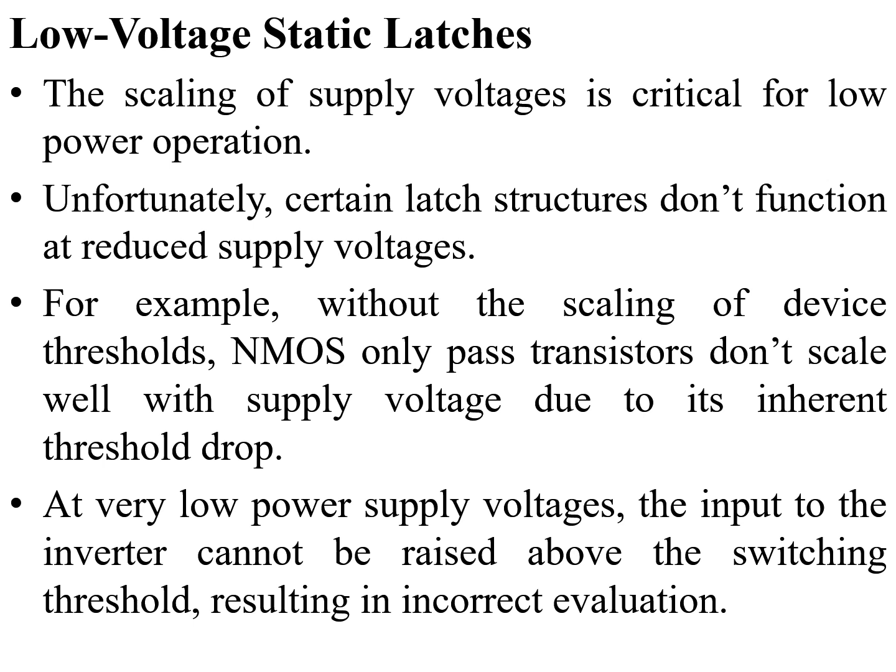Low voltage static latches. The scaling of supply voltages is critical for low power operation. Unfortunately, certain latch structures don't function at reduced supply voltages. For example, without the scaling of device thresholds, NMOS-only pass transistors don't scale well with supply voltage due to their inherent threshold drop. At very low power supply voltages, the input to the inverter cannot be raised above the switching threshold, thereby resulting in incorrect evaluation.